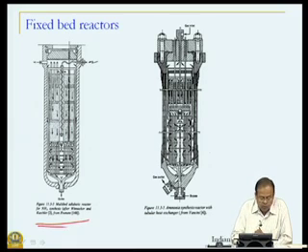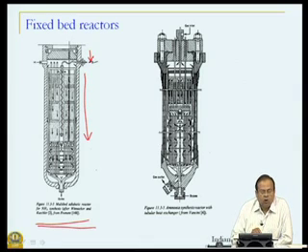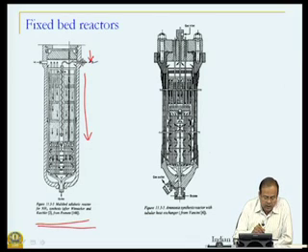This one we discussed last time, that is, what is being done here is the reactants are entering at this point and they are passing through the catalyst bed in this particular direction, but instead of putting all the reactants at the inlet, what we conventionally understand as inlet, let us say axial position z equal to 0, instead of doing that you have several tubes in which cold reactants are added in the middle of the reactor.